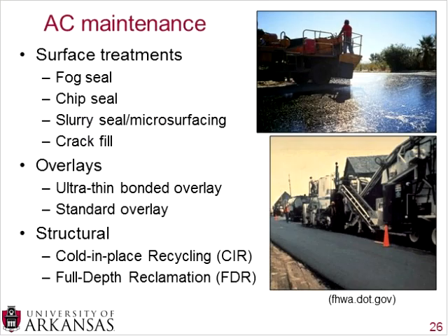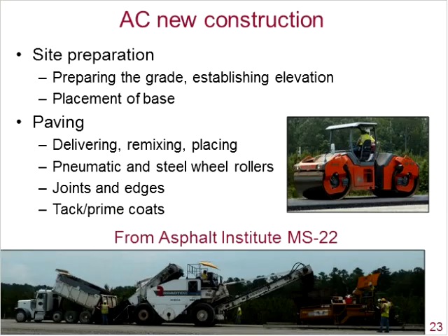So we had a question on slide 23. In this slide, you have your truck delivering the mix. Then you have your material transfer vehicle, or MTV, right here remixing, and it goes into the hopper. And I have not heard of an MTV having heating capabilities. Now that doesn't mean it's not true. I encourage other people to hop in if they may know whether or not for sure. I have not heard of it, but if they don't do it, it probably wouldn't be a bad idea.